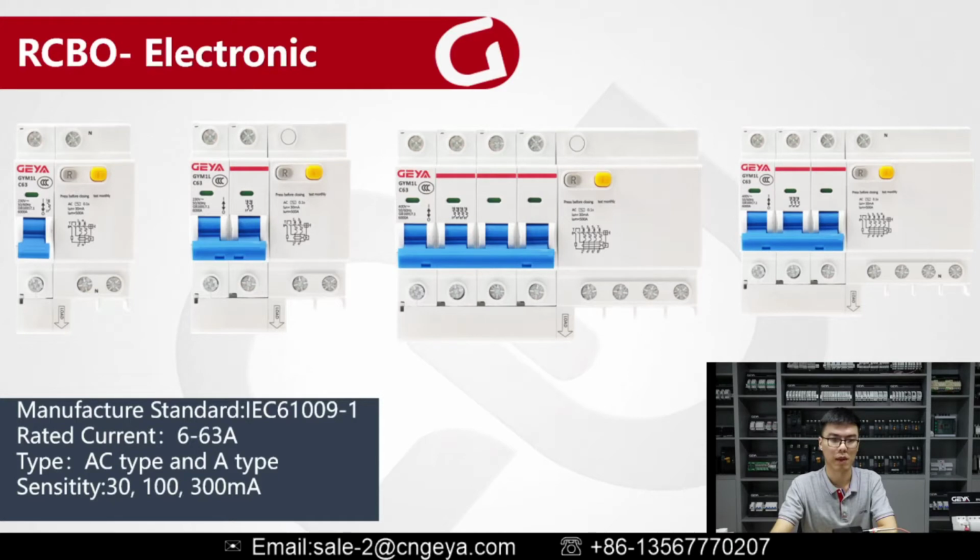This one is manufacturer standard, also IEC standard, but its rated current is wider range than the former RCBO. This one can do from 6 amperes to 63 amperes. Its working type, AC type and A type, also same to the previous one. And the sensitivity we can do is 30 milliamperes, 100 milliamperes, and 300 milliamperes.